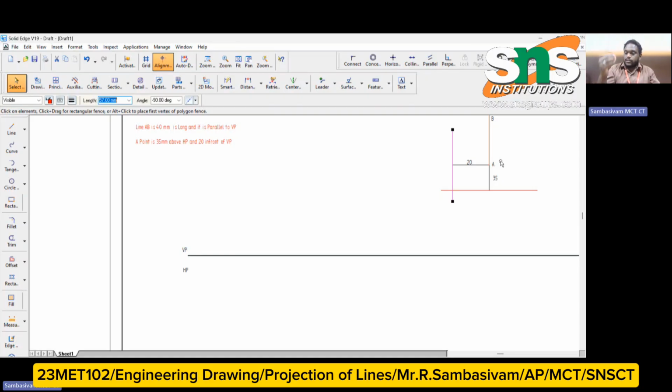So it is a two-dimensional structure right now. From the top view it becomes a point, which is placed below the horizontal plane as a single dot. The line AB is placed in the vertical plane. As per the rules of rotation, the horizontal plane moves through 90 degrees, and once it is moved, the dot lies in the vertical plane.